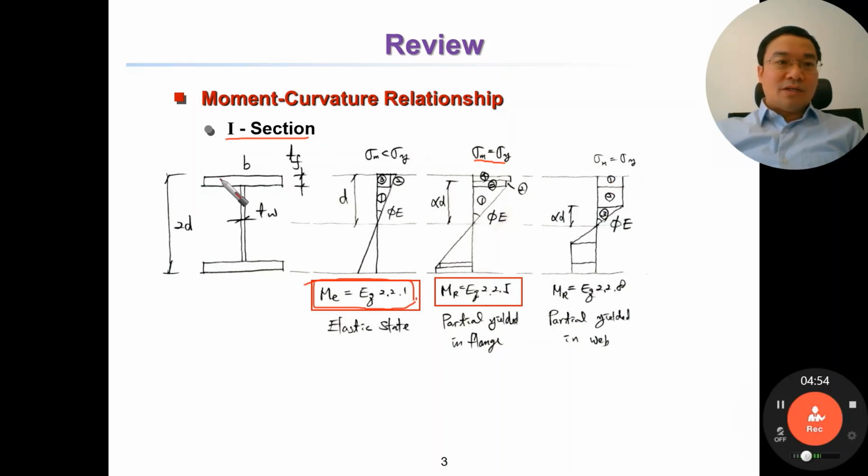One part corresponds to the flange, the second part corresponds to the section in the web that is fully plastic, and part 3 corresponds to the web, but in elastic. Finally we can calculate M equal to this equation in the textbook. Please check.